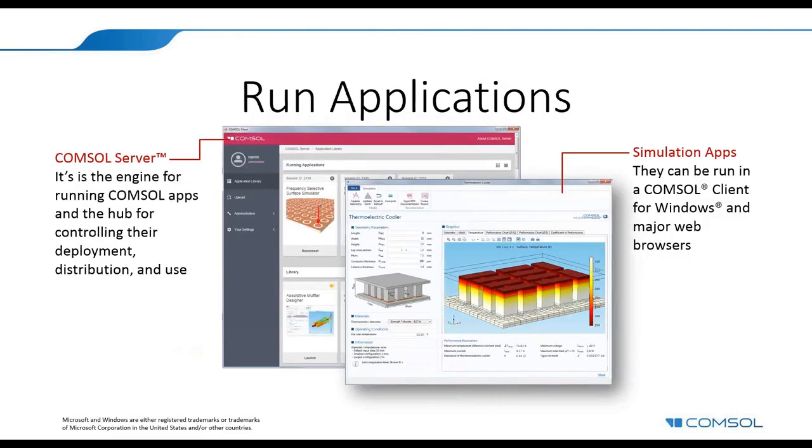the next obvious question once you've created an app is how do you run it and how do you share it? You can open and run an app from COMSOL itself. You can also make it possible for other app users who don't actually have COMSOL installed on their machines to run it as well. And for that, you want the COMSOL Server. And then an app user can install a COMSOL Client or can actually use a web browser to run an application hosted on the server. That makes the app accessible worldwide. Any updates to the app are immediately available to the user. And on this slide, you can see how that same app for the thermoelectric cooler model would appear run in the COMSOL Client.